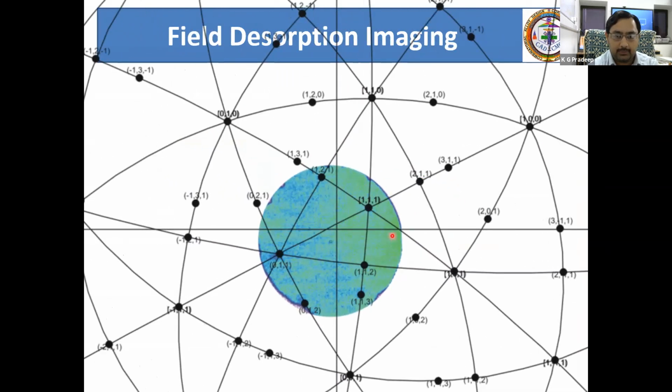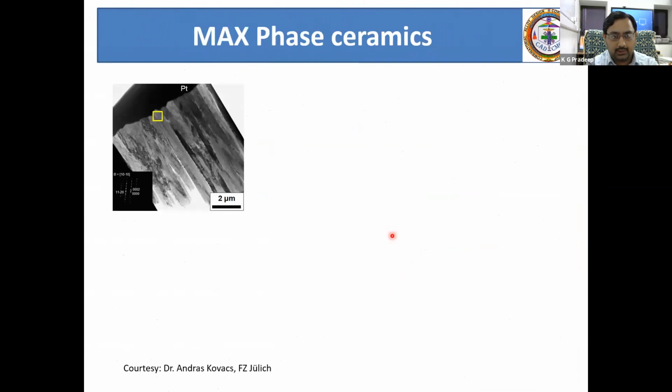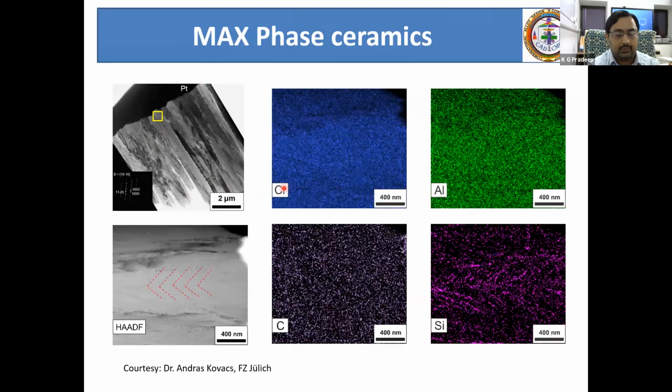Okay, so this is one example where you can now look at the atoms clustering and their crystallography. The similar stuff we have done for other materials. So this is a thin film ceramic, and you can see that there are nanocrystalline columnar grains of thin film, and it has been prepared by dual beam focused ion beam.